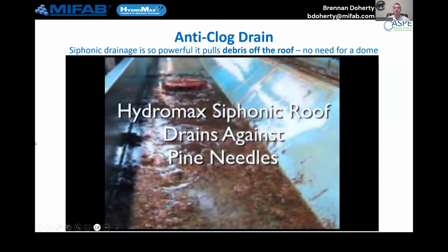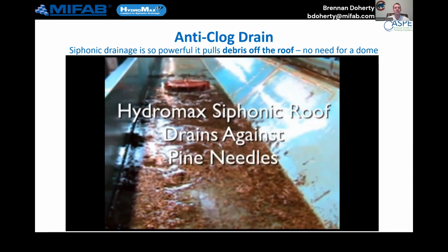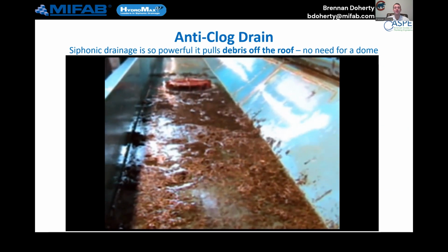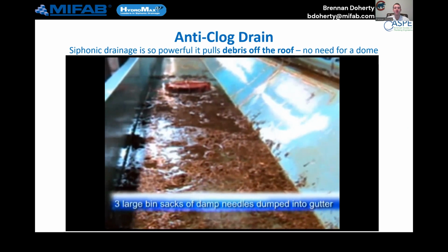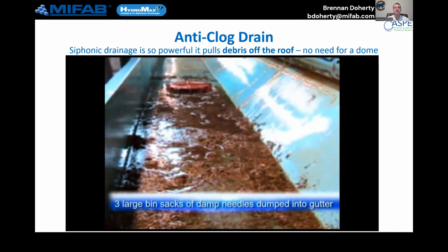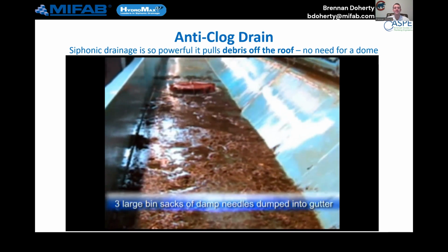What about siphonic drains? In the video I'm sharing with you right now, what we did was we took 3 giant garbage cans full of wet pine needles and leaves and threw it in here to simulate a flash storm. The first thing I want you to notice, there's no dome or debris guard over that siphonic drain.